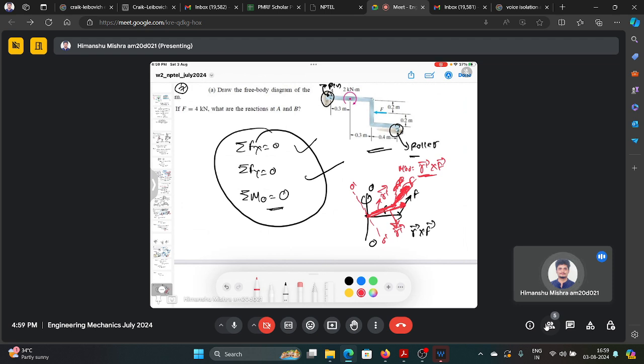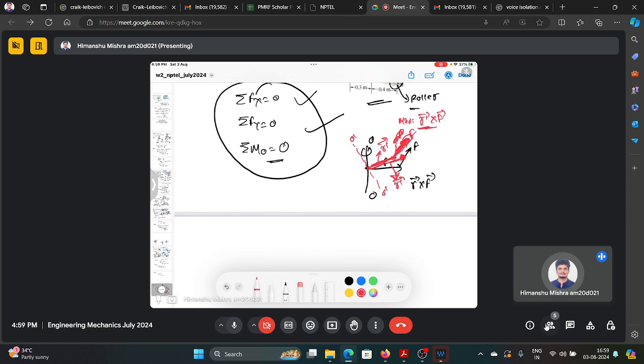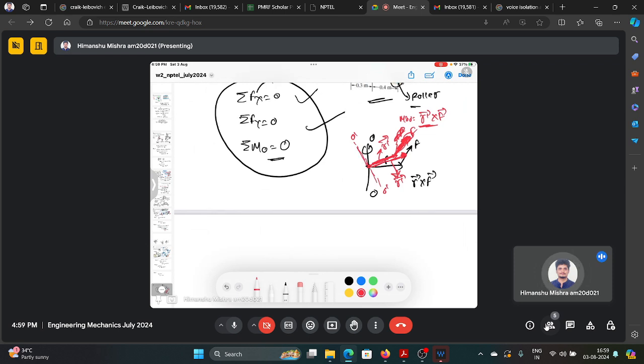I think one way is to do this. Since the axis got changed, you can use the transformation matrix. For example, let's say you have the x and y components of a vector. If you transform to some other axes, x dash and y dash, you have to use a rotation matrix: cos theta, sin theta, minus sin theta, cos theta.